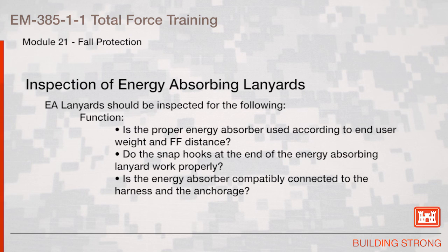Inspection of energy absorbing lanyards. Energy absorbing lanyards should be inspected for the following. For function, is the proper energy absorber used according to end user weight and free fall distance?